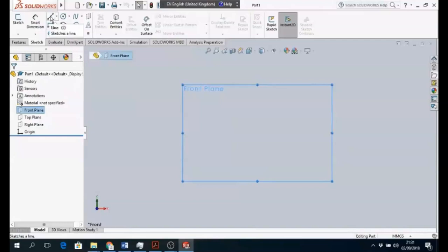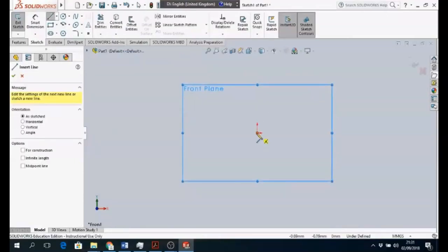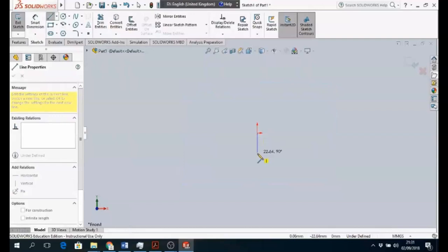First thing we want to do is draw the center line of our mixer. So start off here, and when we go into the page, it shows us the origin here, 0,0. And if we draw a vertical line down from there, if you just draw it down, it'll keep it vertical.